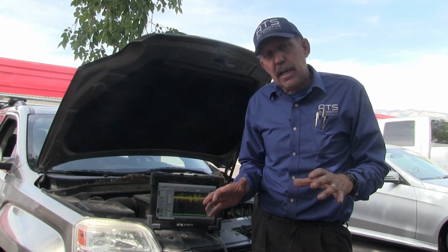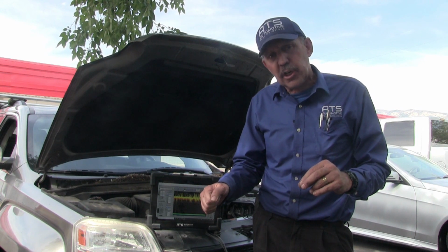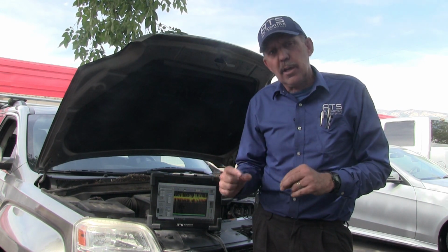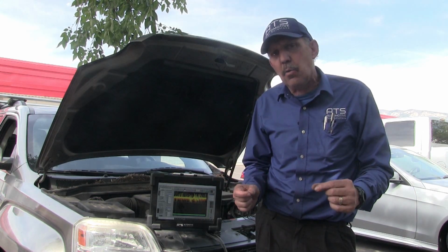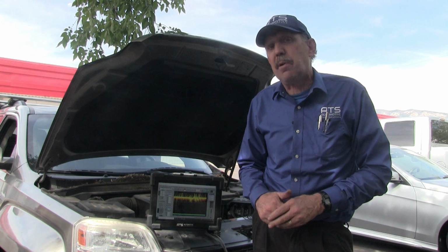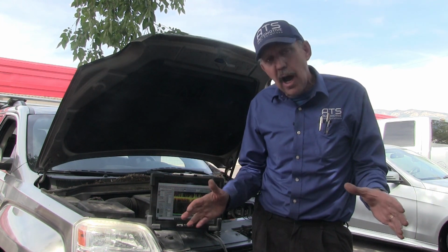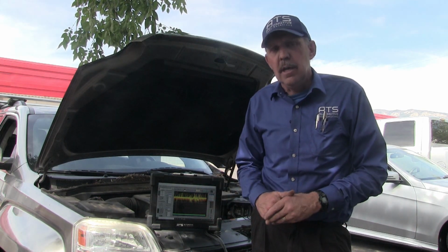I want to put in a voltage output from the scope, and it is a 0 to 5 volt signal, and then we're going to see if it'll pull that signal down. If that signal gets pulled down, then something in this circuit is pulling it down, and we can put all the parts on you want, and you're not going to fix it until we figure out what's pulling the circuit down. So let's go ahead and do that.